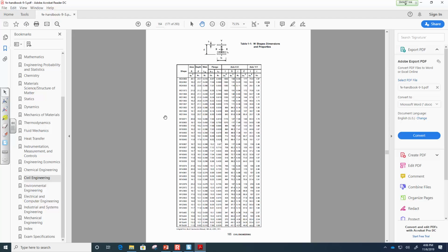An eighth, exactly right. You add a 16th to account for damage to the section, and a 16th for direction tolerance. In other words, you actually drill the hole a little larger than the diameter of the bolt, but we end up also adding another 16th to account for loss.